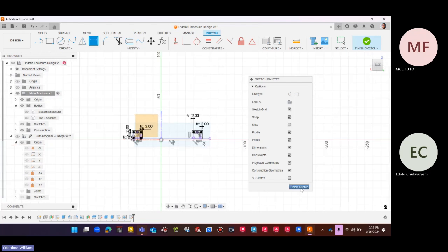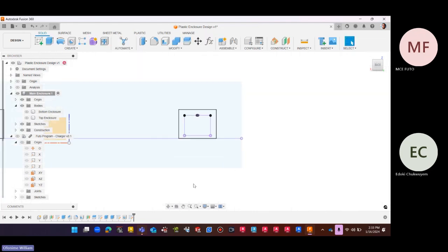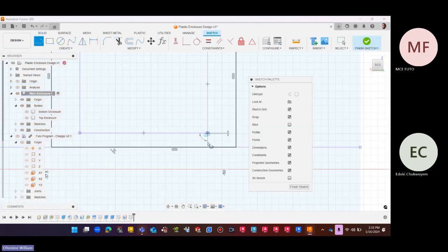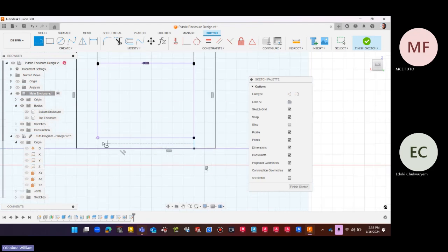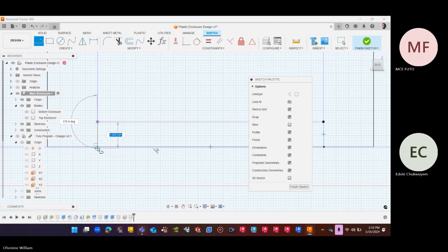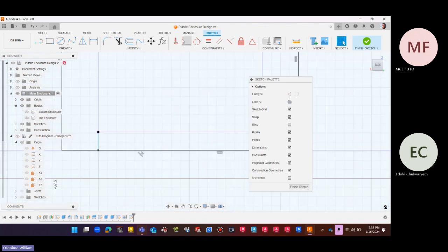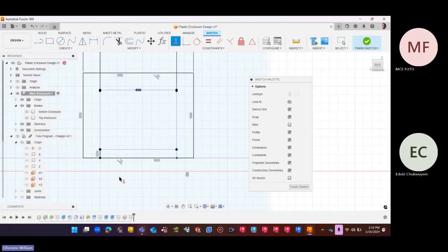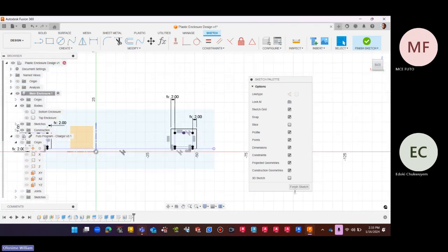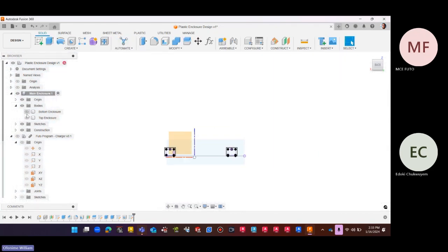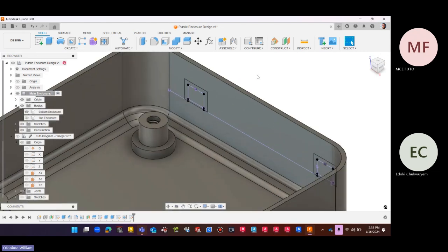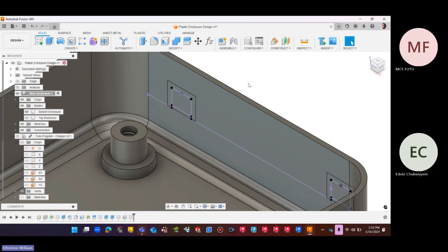So having done that, this is what we are trying to achieve at the end of the day. Okay, one more thing, sorry. Let's click edit. Same thing, you have to close up this part. Same one too. Okay, doesn't look straight. You could use your constraint to arrange that as well. Okay, so we'll do finish sketch. Now, when you turn back on your main design, which is the enclosure, the first thing we'll do is to open up the hole first before building the guide.